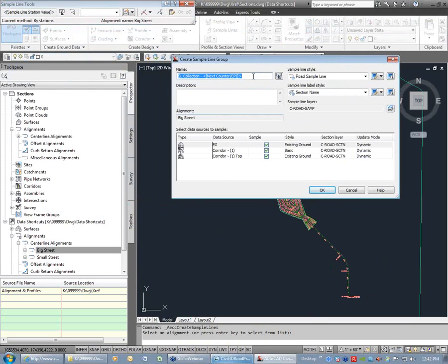But notice here, when you create sample lines, this is part of the procedure that Civil 3D requires. You'll notice I'm getting the existing ground surface, and I'm getting the corridor, and the corridor top surface that came from that X-reference. So somehow they figured out that if you X-reference in the corridor, I can actually extract that information. Which then leads me to believe, well, why couldn't they do this for all objects, and just X-reference it instead of having to deal with data shortcuts? Unfortunately, they didn't do that. So for now, it's just corridor stuff that allows you to X-reference.